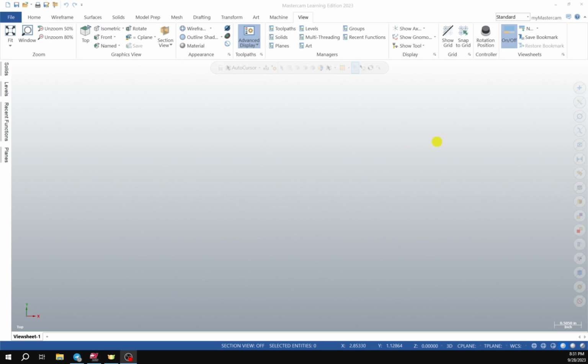You have the choice of changing the graphic window color background. The measurement system should also be set to either inch or millimeter, bottom right corner. To adjust and set these parameters, you need to go to your configuration window and adjust everything there. Now, let's go ahead and do all these together.